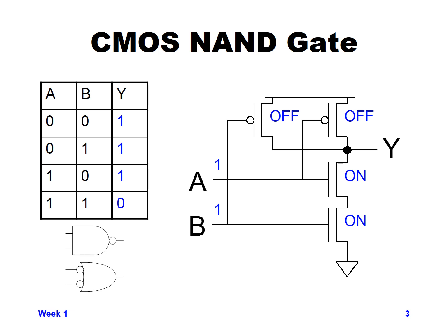Normally with an AND gate, you only get a 1 out if both inputs are 1, and you get a 0 if you have either input 0. A NAND gate is not AND, so it's taking an AND and inverting it. So in this case, if any input is 0, you get a 1 out, and if both inputs are 1, you get a 0 out.